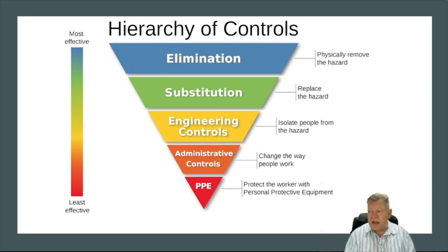So things like guarding, protection, things like interlocks, if you open up a door that a machine comes to a grinding halt, all of those things are engineering controls. Redesigning the process, making sure that a walkway is smooth, putting handrails on so that people cannot easily go off the walkway in the road by accident and so on.